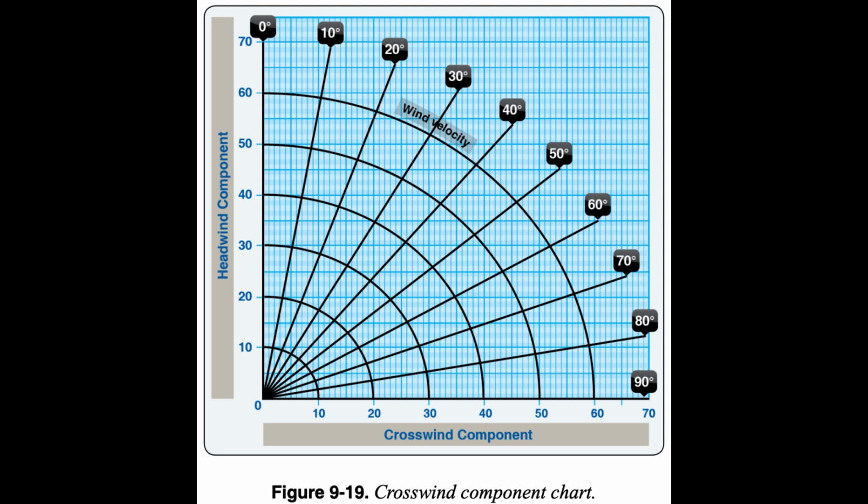Inadequate compensation for wind drift on final approach. 4. Unstable approach. 5. Excessive sink rate or too low an airspeed from increased drag and reduced vertical lift during sideslip. 6. Failure to touch down with the longitudinal axis aligned with the runway.